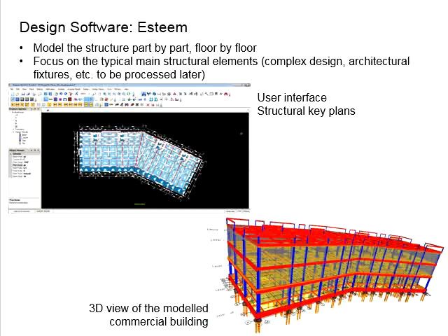The meaning here is, normally we use this software to model the main structural elements, which is the significant part of the structure. We are talking about the skeleton frame system. For those minor parts, as well as the complex design of the structural element or the architectural features, you don't have to incorporate them in the main design unless you are an advanced software user.